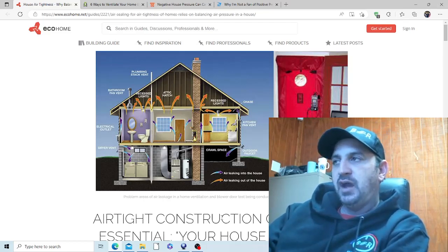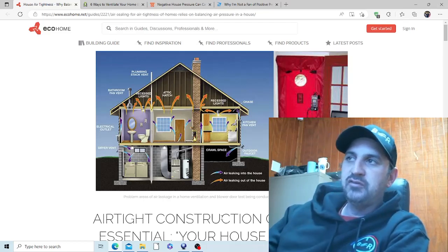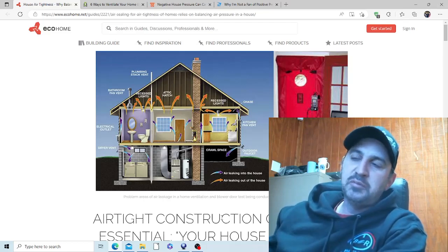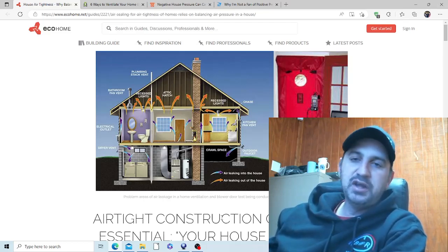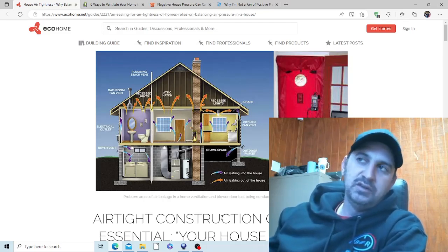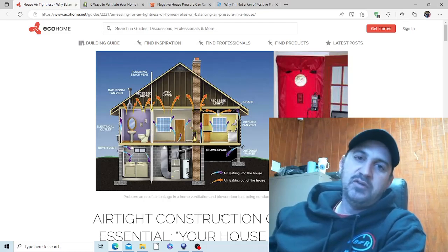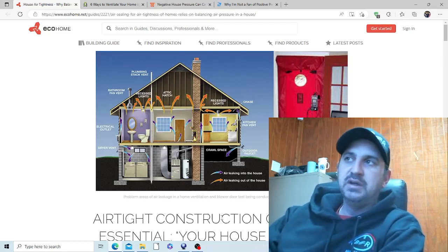So as a starting point, if you notice that you have a lot of the symptoms that we'll go through for a positive pressure home or a negative pressure home, or just bad air exchange in general, we encourage you to find someone that does a blower door test. We don't currently offer them, but hopefully in the future we'll have that set up.